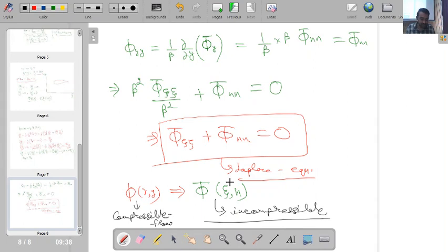But when we transfer into the zeta eta plane, that equation does not have any involvement of Mach number. So it has transformed into an incompressible regime. The same flow situation, which acts as compressible in the xy plane, acts as incompressible in the zeta eta plane. So I can find the solution in the zeta eta plane and then map it back into the compressible regime, because the solution of the compressible regime is more complex.